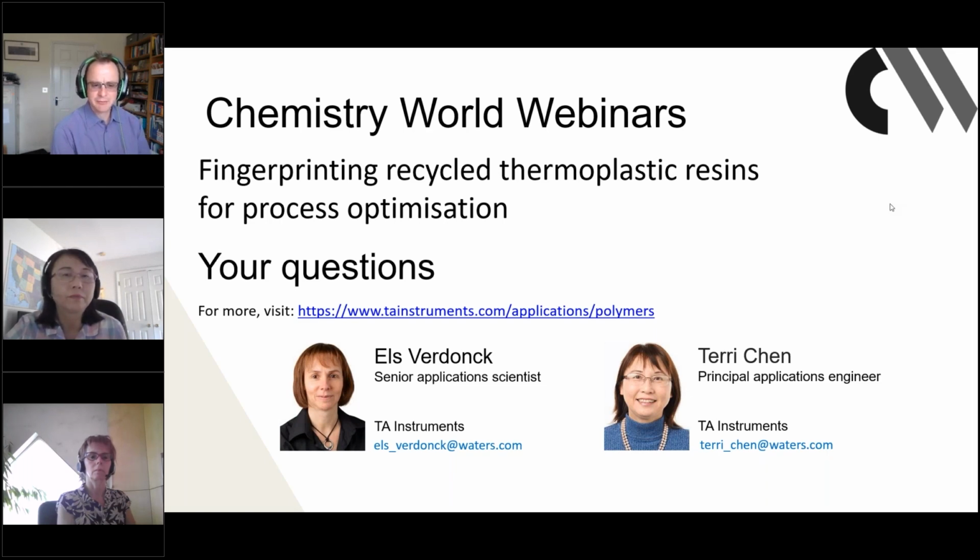Great, thanks very much. And maybe as a follow on to that, if we're talking about blended feedstocks from recycling, can the thermal or rheology techniques give you a quantitative measure of the amounts of different polymers in those mixtures? From the rheology side, we may be able to see that we have certain different amounts of different polymers in this feedstock, using the frequency sweep and testing the data down to really, really low frequency. You will see the shape of the G prime, G double prime curve will look different.